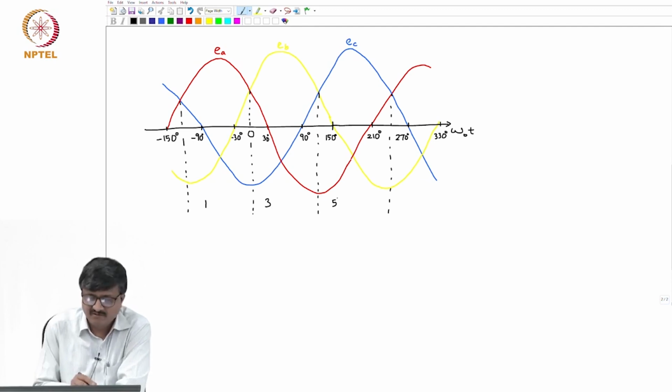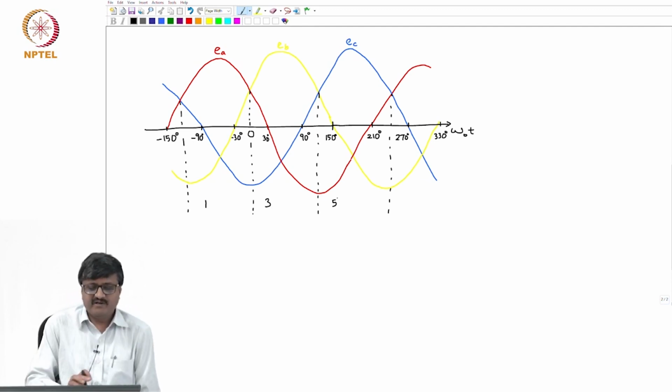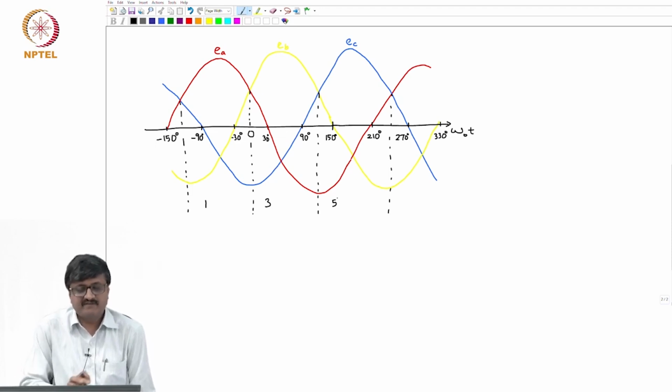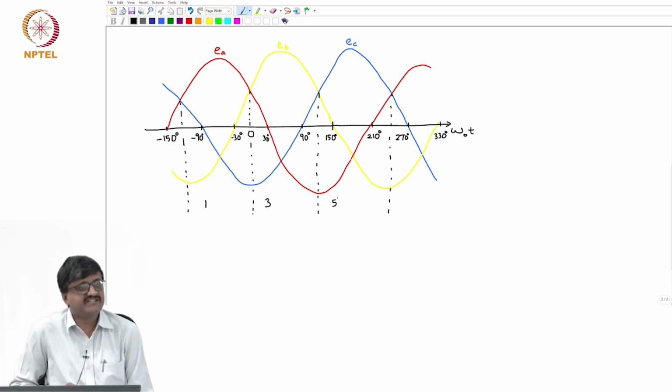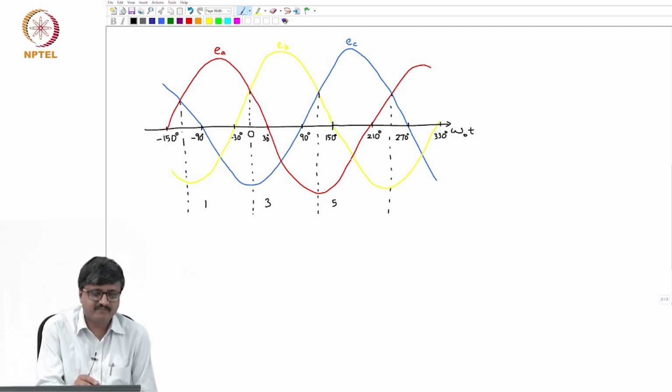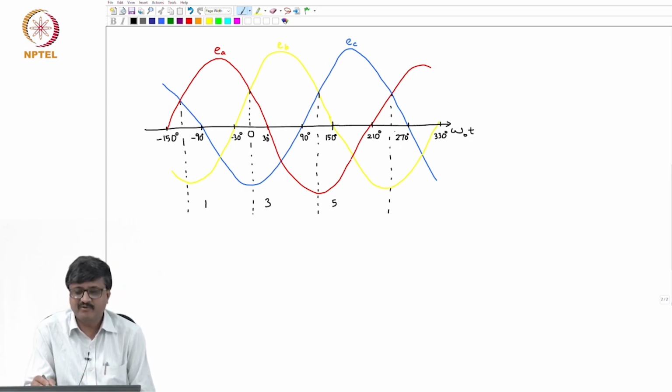Okay. So, now we know which one among the thyristor valves of the upper commutation group conducts. If you have noticed, we have considered one full cycle of 360 degrees. We started from minus 120, though I have not marked it, and we go up to 240, which lies between 210 and 270. So, minus 120 to 240.